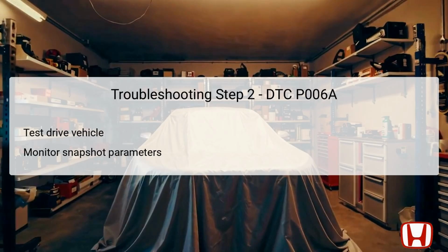Monitoring these parameters allows for assessing how effectively the intake air system is functioning, offering clues as to whether the issue is isolated to the MAP sensor, or elsewhere in the intake system. The third step focuses on inspecting the intake air system and its ancillary components. This involves examining the condition of connections and identifying any visible damage within the positive crankcase ventilation (PCV) system.